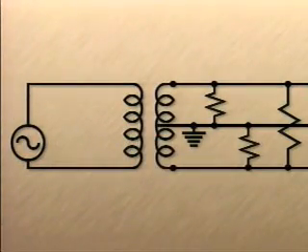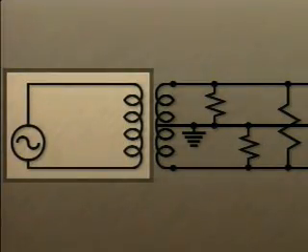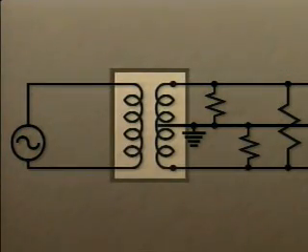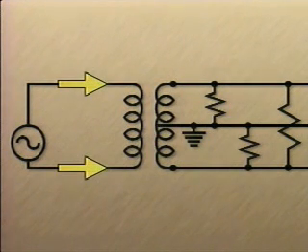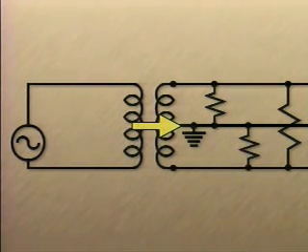Since it's often desirable to have more than one voltage, the three-wire single-phase system was developed. The three-wire system makes it possible to have two different voltages from one voltage source. The component that changes a two-wire single-phase system to a three-wire single-phase system is a transformer. As this illustration shows, two lines come into the primary side of the transformer, and three lines come off the secondary side. The middle line on the secondary side is called the neutral line. It divides the secondary into two halves.